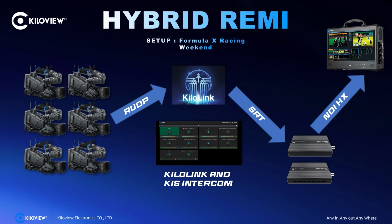Then we send the SRT back to the venue where we have the two MG300s. Those media gateways allow us to bring back those SRT feeds into NDI-HX, allowing us to not have any hardware solution to get our signal back into our vMix system. And this shrinks down the setup a lot, and it's an easy to use solution and an example of how you can put Kiloview into your setup and have some remote production involved.